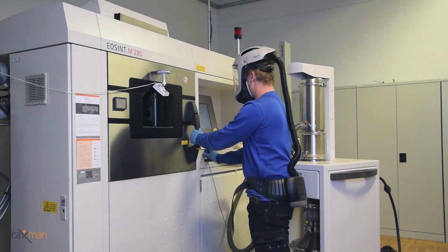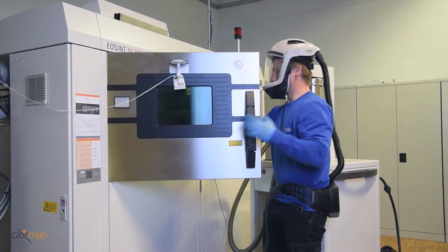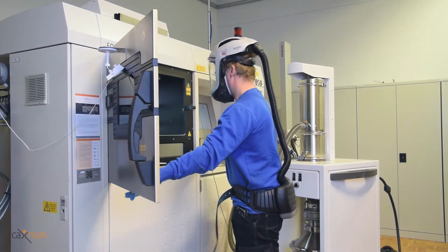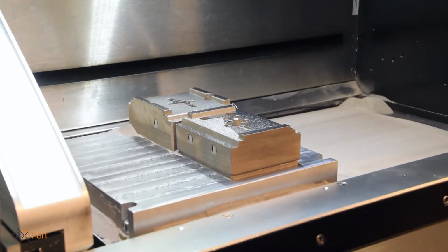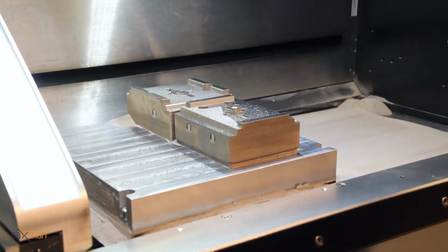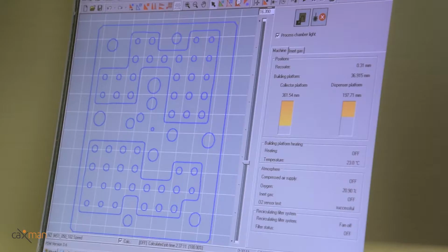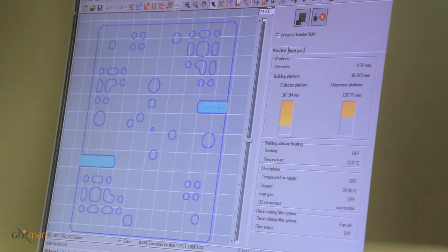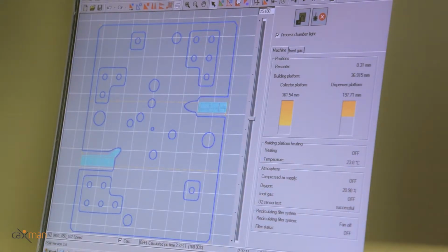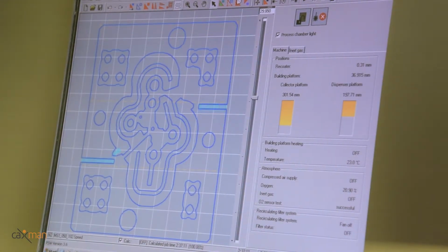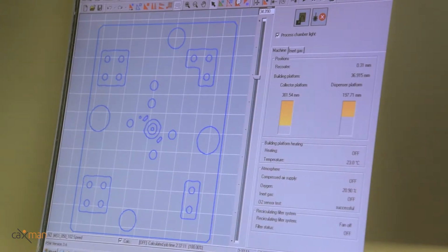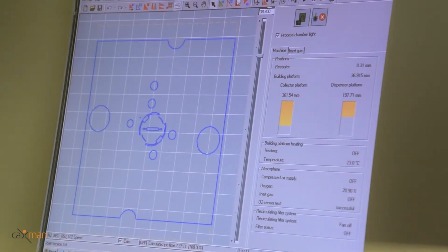When the parts are big and heavy, the economical consequences of errors in the printing process are severe, particularly if the faults occur late in the process. With CAxMan, we have the opportunity of simulating how the parts deform during printing, and we can adapt the design accordingly or optimize the orientation before we start. Another important function of CAxMan is in designing internal voids and cooling channels, as well as openings and channels to evacuate trapped powder.